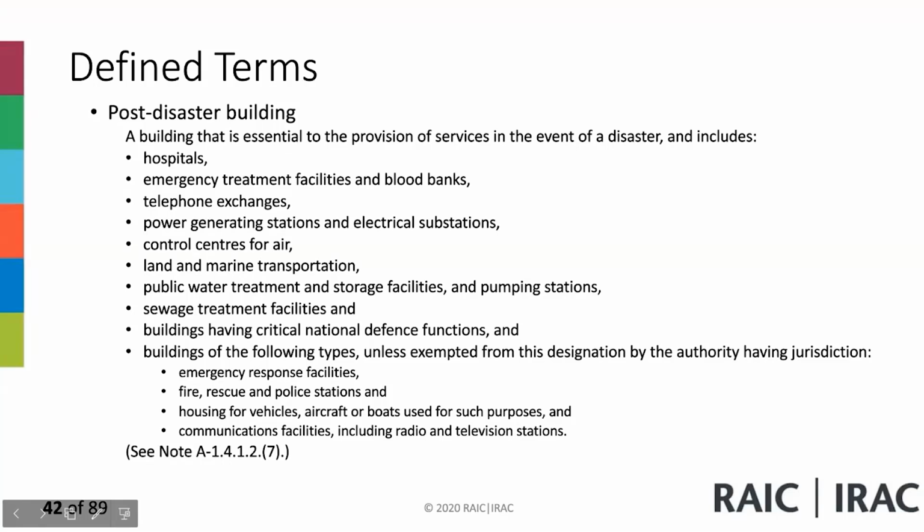Okay. Sprinkler assemblies are acting as a closure. So if you want to provide sprinklers as an alternative to doing a fire protection rating or providing fire resistance rating, then that's an alternative solution.